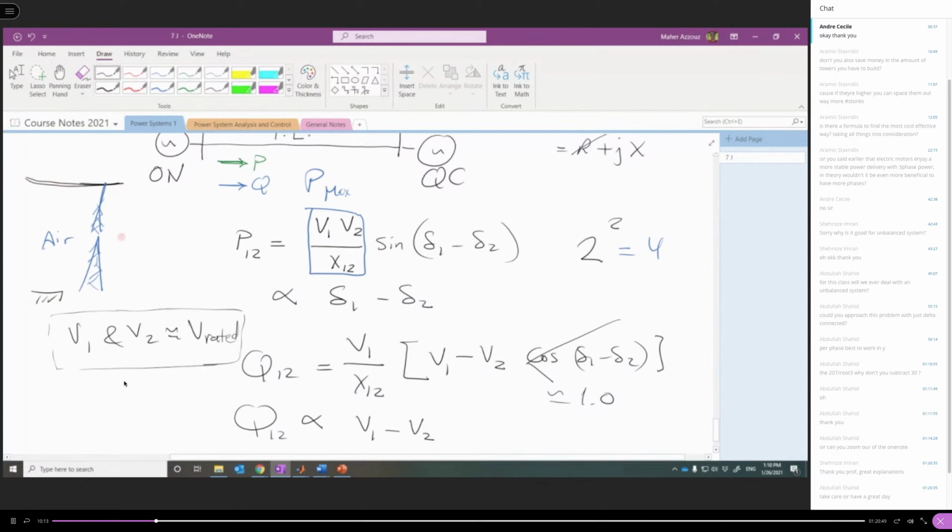So doubling the voltage means we have to double the height, which of course adds to the cost of the transmission line, the cost of insulators, but we save costs in terms of the land requirements, or building a double circuit to serve the same load.